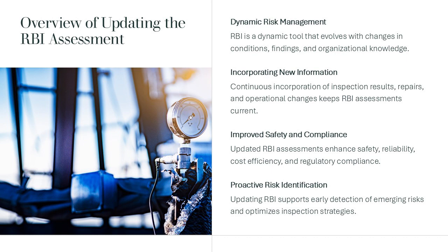It also supports proactive identification of emerging risks, such as new or accelerated damage mechanisms caused by subtle changes in operating conditions. Ultimately, maintaining a current RBI assessment helps organizations prevent unexpected failures, optimize inspection scope, and demonstrate due diligence in managing asset integrity across the lifecycle of equipment.